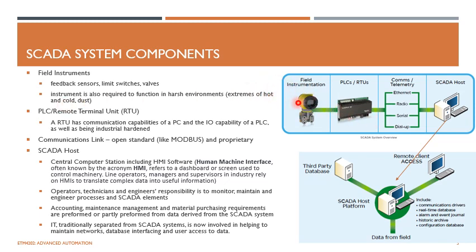Then these field devices are connected to a PLC or RTU. PLC stands for programmable logic controller, and RTU stands for remote terminal unit. The only difference between the PLC and RTU is that the RTU has embedded communication capability compared to a PLC, which means they can transmit the data via different kinds of communications. Sometimes it could be wireless communication. So it has the capability of a computer and the same I/O compatibility as a PLC.